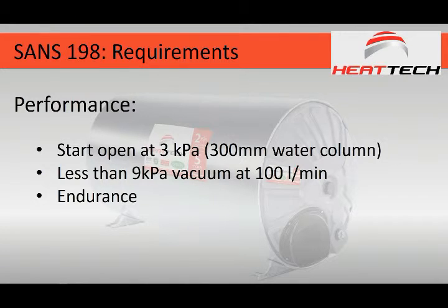Endurance is always an important thing. It is to put the vacuum breaker through its paces. Let it suck air, close. Draw a vacuum, close. Draw a vacuum, close. I cannot recall the number of cycles, but it's quite a large number of cycles. So again, if it's been through the standard, if it's been tested, it will function for a long time in the system.